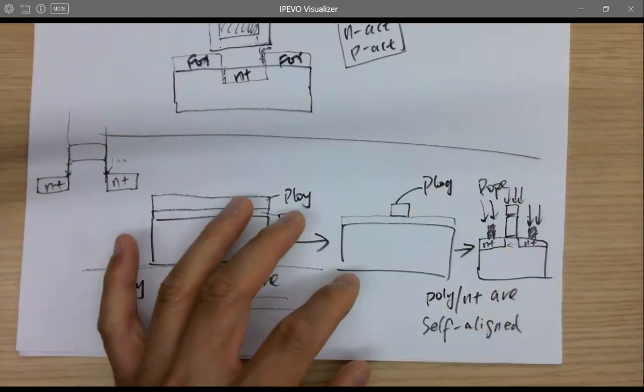Okay. So in that case, these are considered as metal one. So the via is a diffusion to metal one via. That's why I can use the blue color, which is metal one, to draw a line to connect all the vias. Make sense? The via is having a contact with metal one.